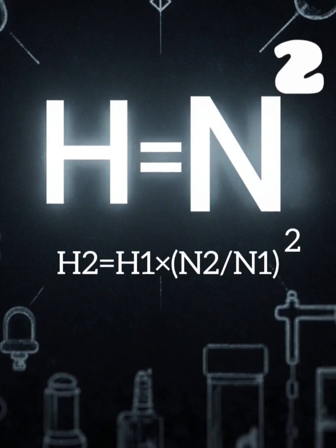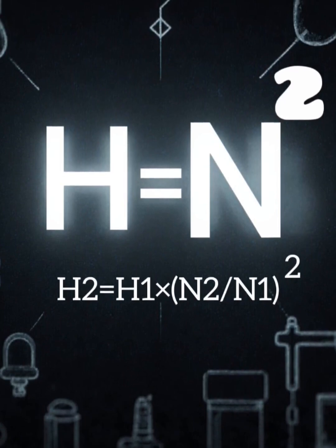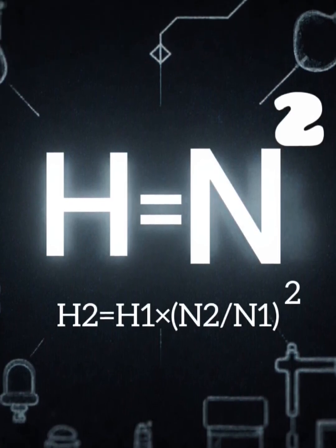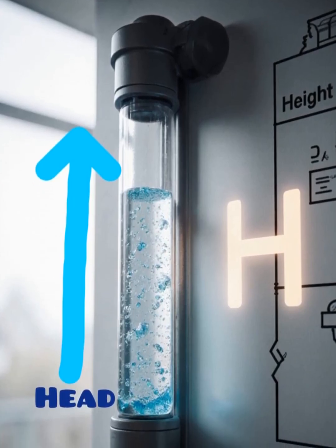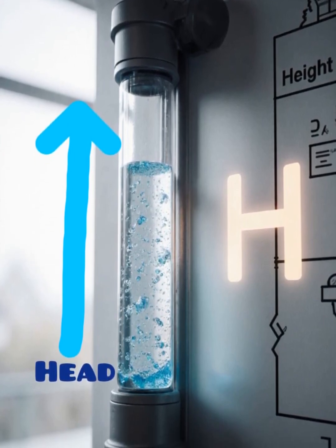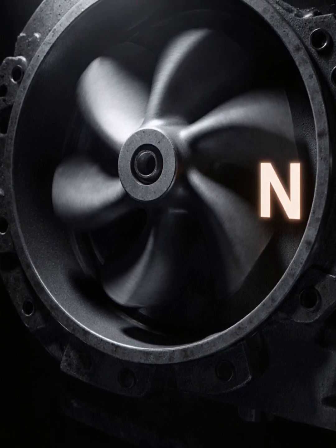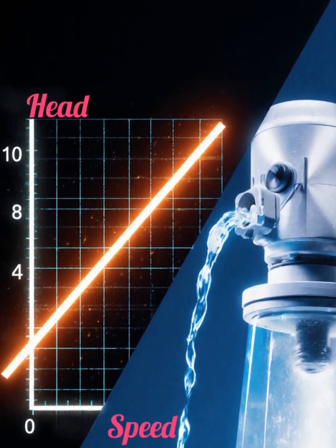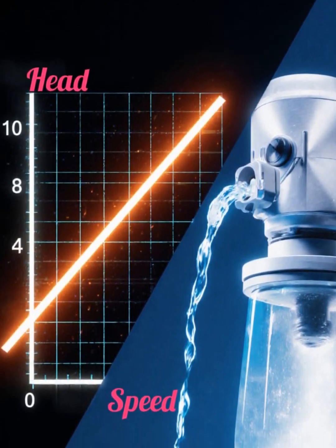This relationship is mathematically expressed as H2 divided by H1 equals N2 divided by N1, the whole power 2. Here, H represents the pump head, which is the height to which a pump can raise fluid. The N denotes the rotational speed of the pump's impeller. This quadratic relationship signifies that a small change in speed results in a much larger change in head.